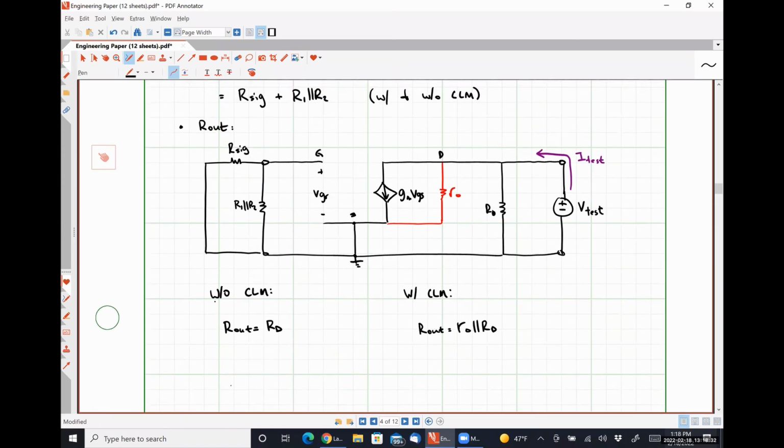Mm-hmm. Okay. Yes, so these circuits as an amplifier are what are called small signal amplifiers. So what we are doing in truth is we are perturbing the DC operating point by a little bit and seeing what comes out. Okay. So we have effectively an AC perturbation superimposed on top of our DC operating point. And we are analyzing these circuits right here, only looking at the small signal or AC representation.